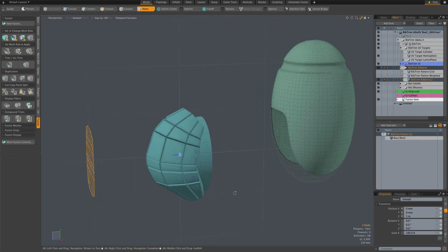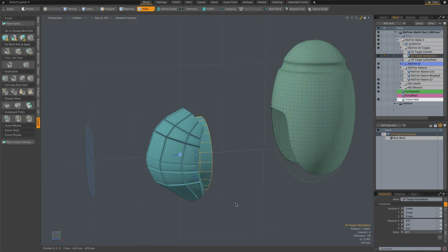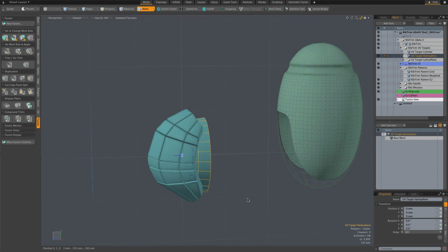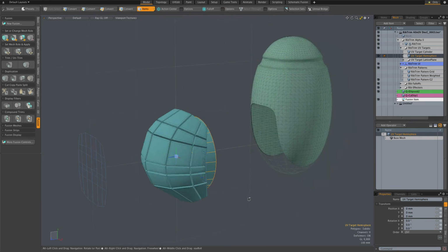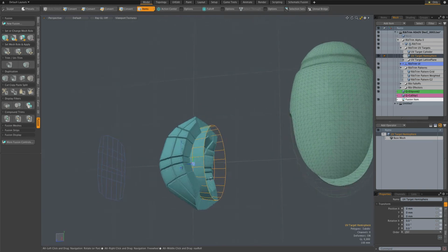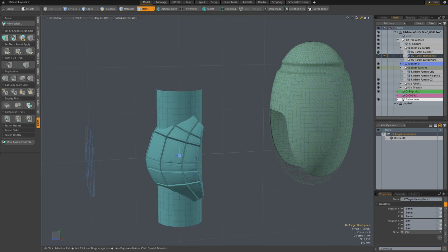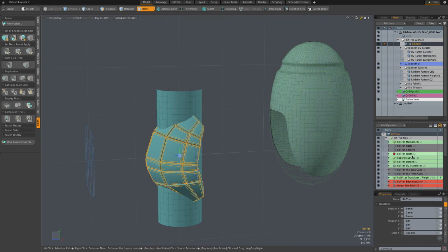In a very similar fashion, we can change the UV target mesh. So that's it sitting there, that hemispherical thing that we distorted to fit on the ellipsoid in the original intro video. But again, it's just a mesh. I can hide it, show it. And there are a couple other targets here. We'll look at using this cylinder instead of that hemisphere. So I'll make it visible here again. It doesn't have to be visible, it just helps us see what's going on. Go back to the RibTrim assembly itself, and